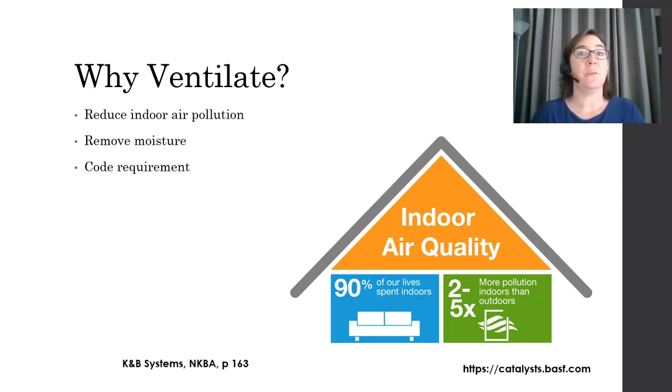We also need to reduce moisture. And this is important specifically in kitchens and bathrooms, which are great producers of moisture. We've got boiling pots and dishwashers in the kitchen. We've got showers and steam saunas and toilets in the bathroom. All of which are bad for the building environment and also can foster mold, which is bad for the indoor air quality. Finally, we must ventilate because it is code required for those same reasons, that it's going to keep our occupants safe.